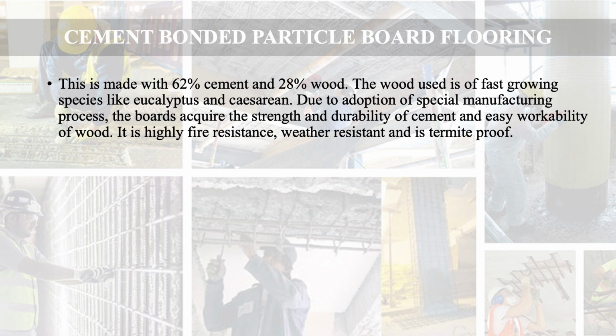This is made with 62% of cement and 28% wood. The wood used is of fast growing species like eucalyptus and casuarina. Due to adoption of a special manufacturing process, the boards acquire the strength and durability of cement and easy workability of wood.